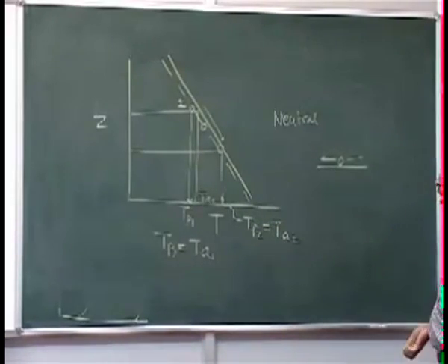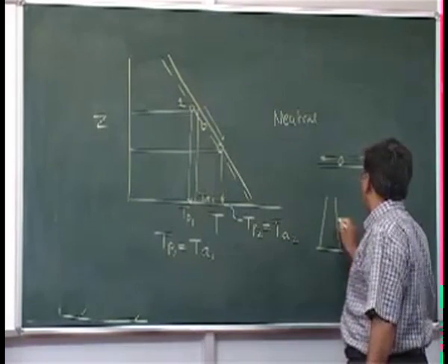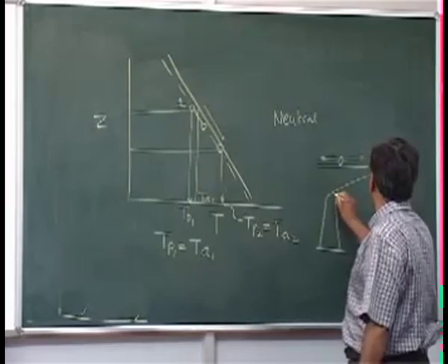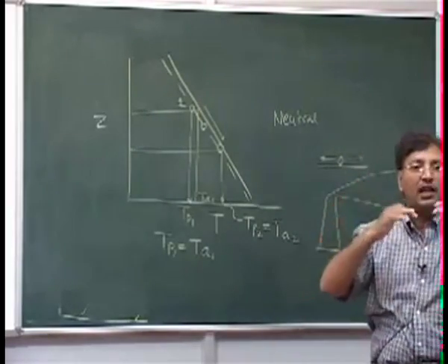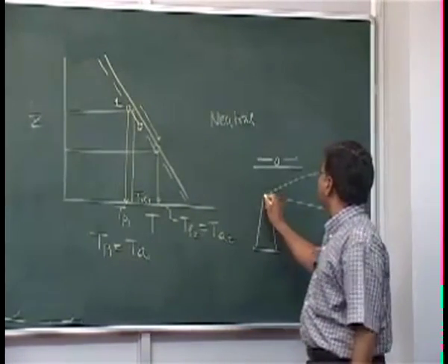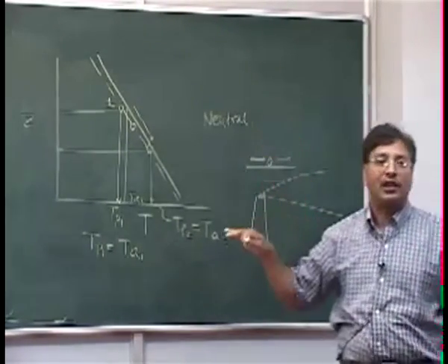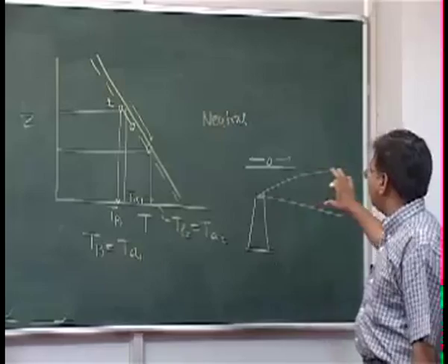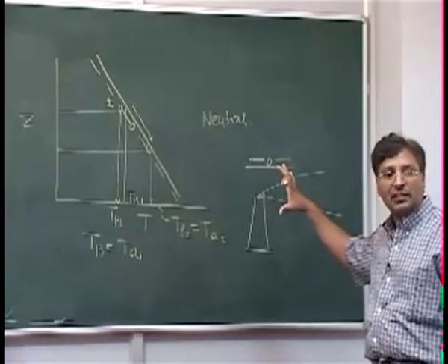This is the neutral condition, and this is what you typically see with chimneys, dispersing a little bit on both sides and stopping there. But the plume is not dancing up and down as we saw in the earlier case. Here you see it traveling nicely as a conical shape of dispersion.